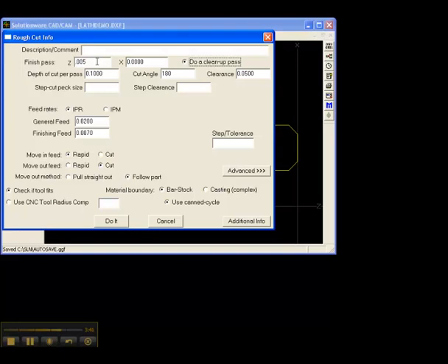On the next row down here, I'm sorry, I skipped over the X stock. Generally speaking, on the face rough, we don't have to worry about that. For the earlier style Mazak users, that is the controls Fusion 640T and below, you only get one set of stock amounts. FinX, FinZ appears on the common unit. So for T Plus and T32 and such forth, I'd recommend you go ahead and give it some X stock anyway. These values, the stock amounts for your first rough cut, will appear at the top of your Mazak common unit. Again, that's for the earlier style Fusion 640T and below Mazak programs.